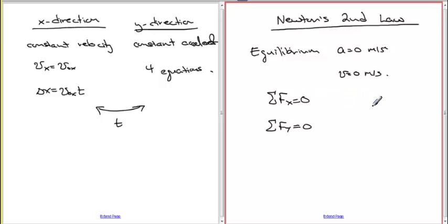And so the only kind of problem we can really do that has this kind of system is where you have 3 or more forces that are acting through a common point. So if you remember the problem we had, you had a mass hanging from a rope, and then 2 ropes were holding it up, and they all connected at this one point. And now that you know about torques, there's no torque made from a case where all the forces go through a single point, because there's no moment arm.